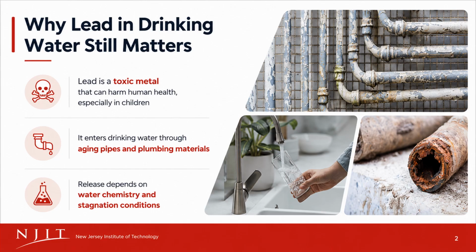So even if the water leaves the plant in good condition, the chemistry of the water can still affect what happens inside the pipe. Things like pH, pipe condition, and how long the water sits in the pipe can all change how much lead is released. That's why corrosion control matters. The goal is to adjust the water chemistry so less lead gets into the water before it reaches the tap.